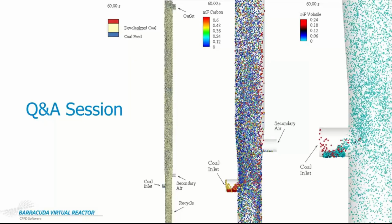I'm going to start here with the question asking, could this be modified for MSW or biomass? MSW, municipal solid waste, I believe. And if so, how? Shashank, would you like to take that one? Yeah, absolutely. In fact, this is a great setup to do that. All you probably have to tweak is a few of those reactions itself and some of the kinetics. But generally, what you'll observe in literature is some of the char gasification reactions are all taken from coal combustion in general. So several of these reactions can be used as is with a few tweaks here and there.